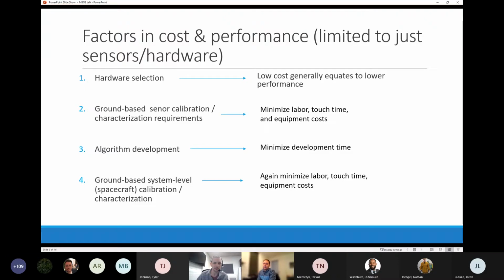And then number 4, ground-based calibration and characterization. There is the sensor itself, that little chip. You can get a development board or something very simple to test that chip. But ultimately, it's going to get integrated into a real satellite subsystem, which will get integrated into a satellite. And these are directional sensors, so I'll take misalignment as an example. How do you know how it's aligned in the vehicle? When you start soldering it to a board and then bolting that board to something else, what's even your reference point? You can get these errors that stack up. So you need to figure out ways to back out those errors, which is one aspect of sensor calibration, without driving a ton of cost. If you buy a $10 chip and then it ends up costing $1 million to go to a facility and calibrate it, then not a great benefit.